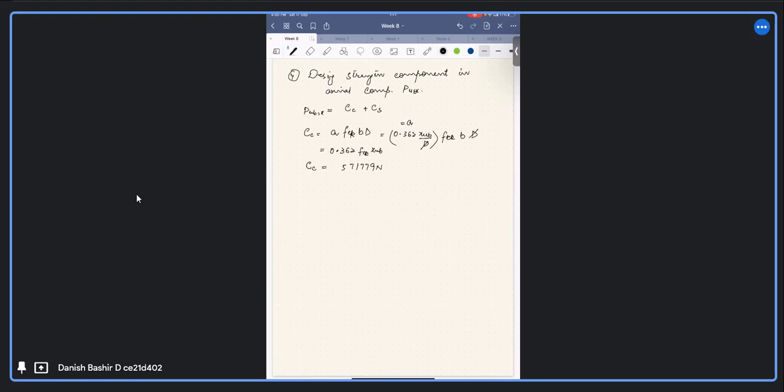Okay, this is the contribution from the concrete. Contribution from the steel, CS, will be the formula. We have to apply summation, I running from 1 to 3. These are 3 rows of steel, CSI from the individual CSI. And CSI is given as summation of FSI minus FCI.